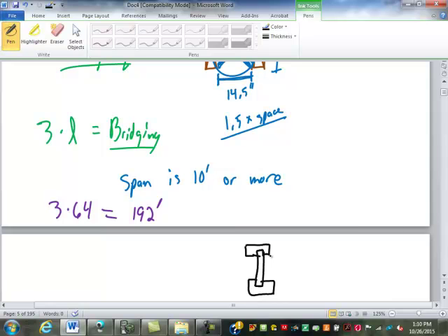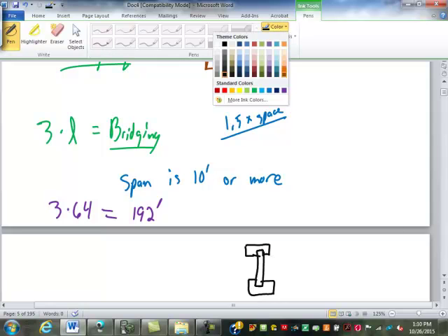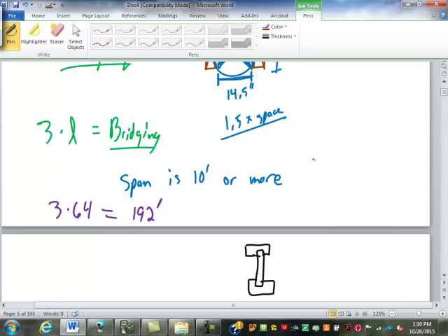Okay. So I mentioned strong back. This is not very symmetrical, but your strong back bridging for TGIs is sometimes done this way. Even with TGIs, it is best to do the X for bridging, but a lot of people just use a strong back bridging where they cut a block.